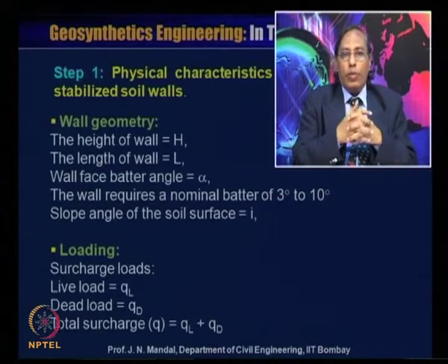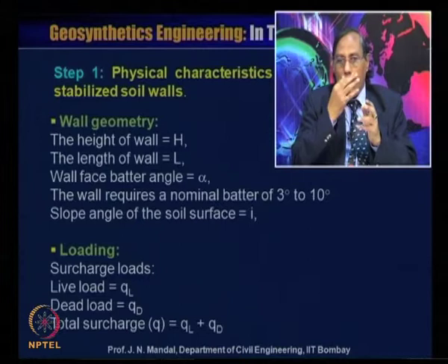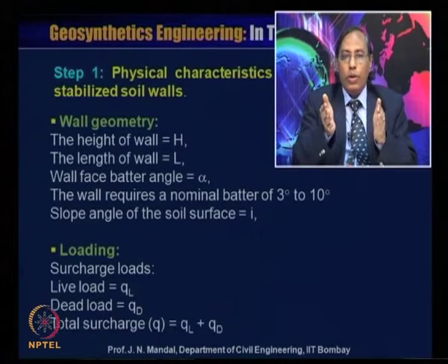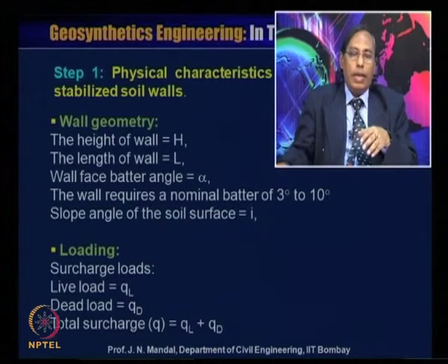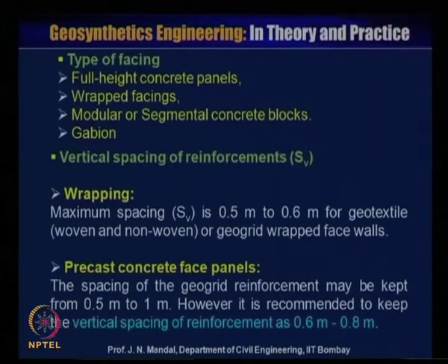And you should also consider what the loading will be. That means the surcharge load. If there is a live load, it is equal to QL. If there is a dead load, it is equal to QD. So the total surcharge load you have to take into consideration will be the summation of the live load and the dead load.